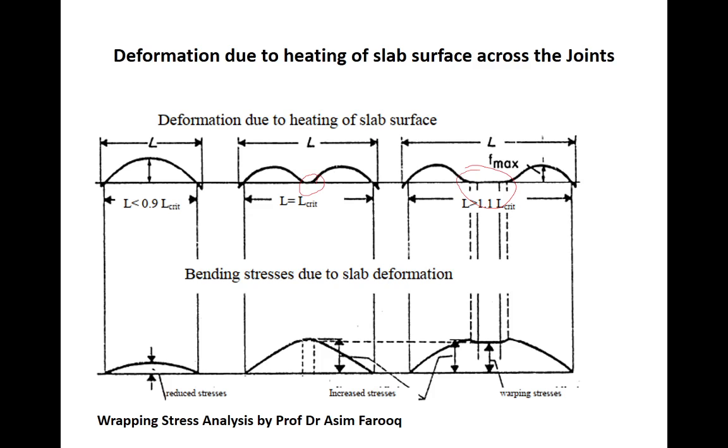These were counted because of the temperature variation, while the next one tells us that the total length is greater than the critical length. So basically L critical means the critical slab length, which is assumed to be rigid support along the slab edges. Okay, in very short, in the last figure, because of the changes in the heating pattern, the slab doesn't have enough time, because that specific middle portion is under continuous warping stresses. Okay, so we have an increasing pattern, and then we have the lower temperature time, and then it again decreases.